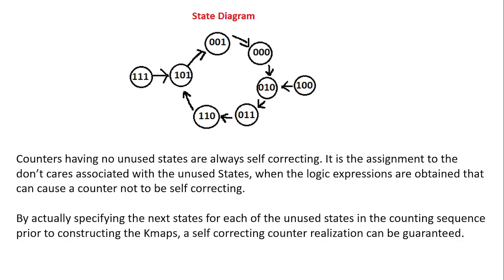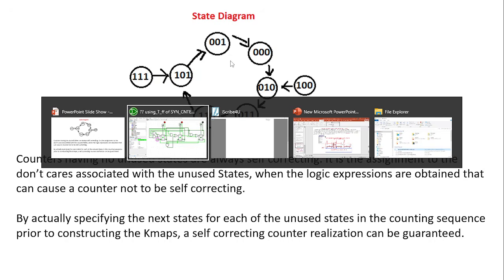Now, let's start with how to design a counter which is self-correcting from the beginning itself. Design a mod 6 self-correcting counter using T flip-flops.